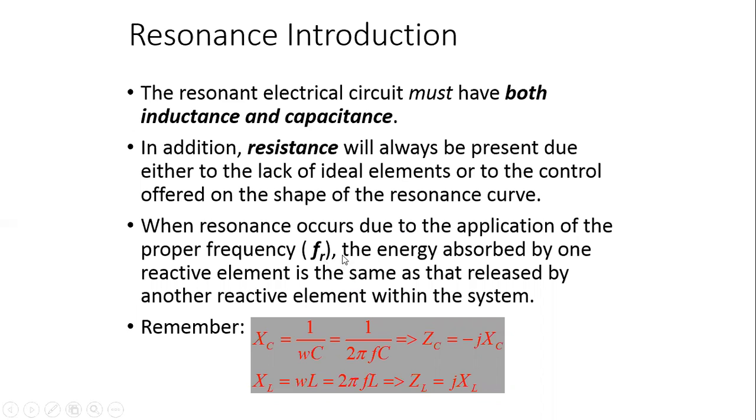Simply, we need to know that whatever we mention at resonance will be treated as a resonance circuitry. Here we can find Z easily by calculating XL and XC. Once you get Z, the other parameters can be easily calculated. If you are thinking about XL, then Z will be ZL. If you are thinking about the capacitor, that is XC, then Z will be treated as ZC. Likewise, you can calculate these parameters, XL and XC, to calculate the impedances.